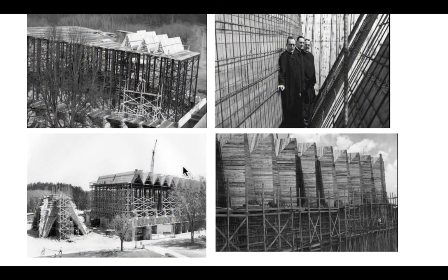Here, in the construction shots, you can see them building the formwork, and I think you get a sense for the way the structure works really well. Again, in each one of these girders that's being poured across the top, there's going to be basically a compression flange along the top fold and a tension flange along the bottom. And then that flat plate is going to work as a flange toward the top and bottom, but more and more as a web toward the middle.